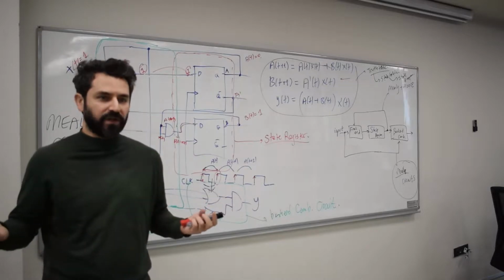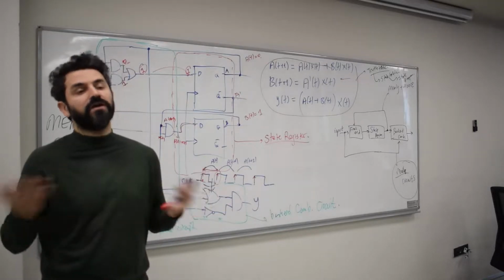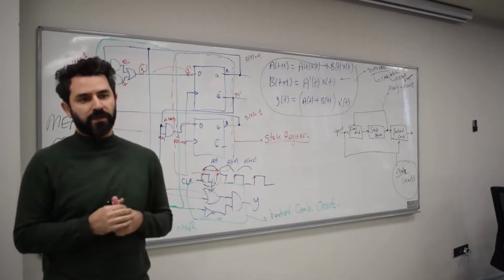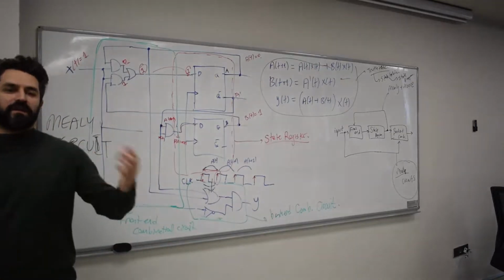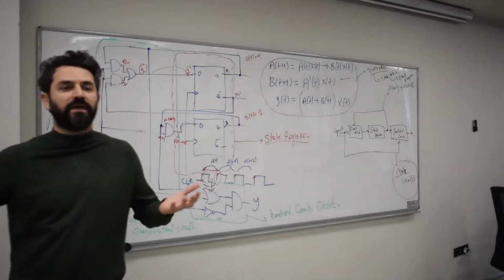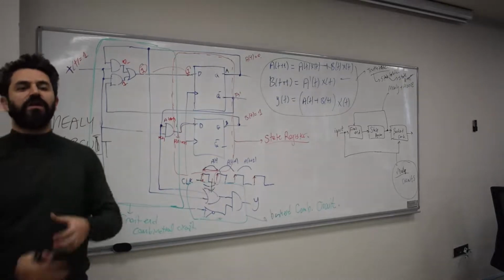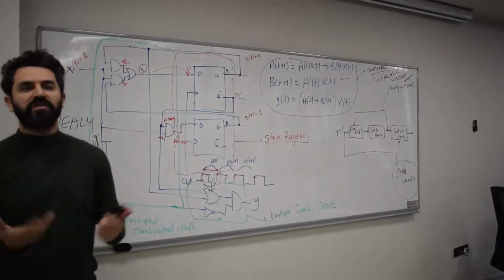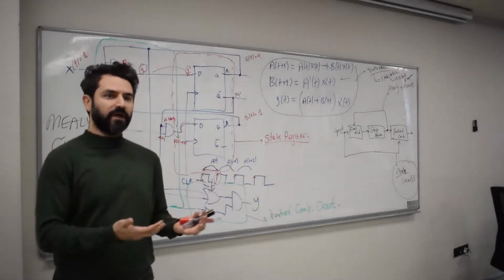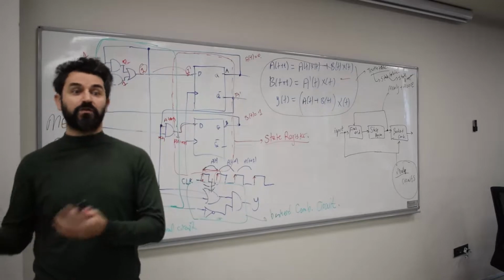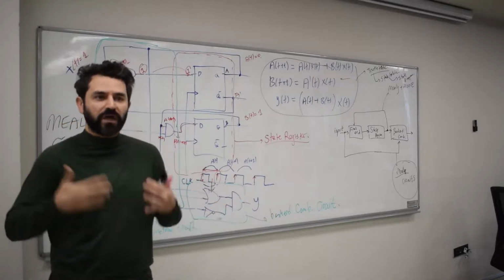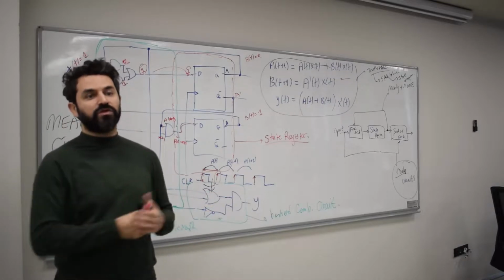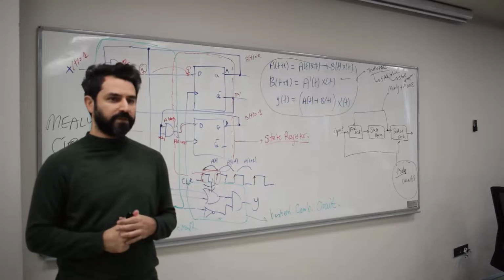In magnetic storage devices, for example, runs of ones and runs of zeros are limited because of this particular synchronization problem. Okay? And there are different codes for that. We don't send this data as is. We basically go through some kind of transformation, some coding, so that we get these constraints on the bit streams, such as runs of ones cannot be greater than 7, and runs of zeros cannot be greater than 0 and smaller than, for example, 2. Those types of constraints can be imposed on the data so that you can have these communication and data storage devices work properly. Is that clear?